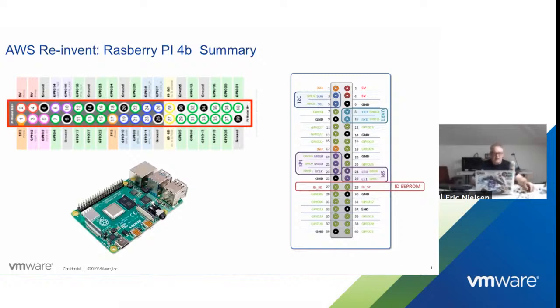So the first thing any good board would have is what we call a power rail, right? So there are 2 power rails that live on the Raspberry Pi. There's a 5-volt power rail and a 3.3 volt power rail. So understand that 5 volts typically run bigger things, but a lot of the sensors will run on either one.